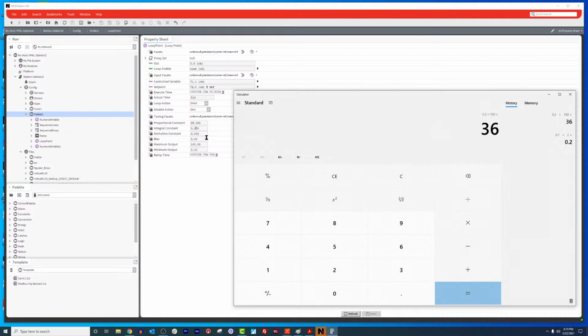That's when folks ask me, how do you figure out your I value? How do you know what you want your I value to be? Well, let's say we have a PID loop for a pressure loop. Super fast, right? Pressure loops normally react in 30 seconds, and it's normally an error of like 0.5. So 0.5 times a setting of 1, which is what I like to use, is 0.5. Now let's times that by 30 seconds. We're going to get 15% output in 30 seconds on top of probably a pretty big proportional band.